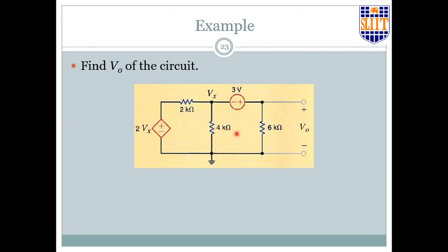It's the same case we have to do in nodal analysis if you have a dependent source. But keep in mind please that you can't use the superposition theorem and things like that when you are having dependent sources.